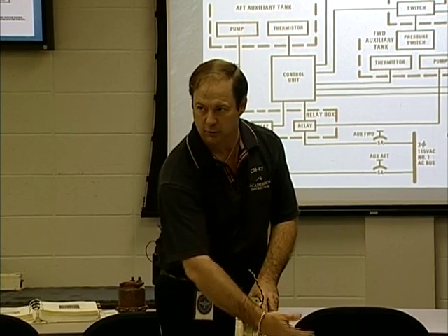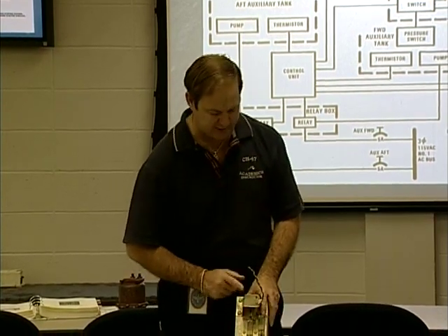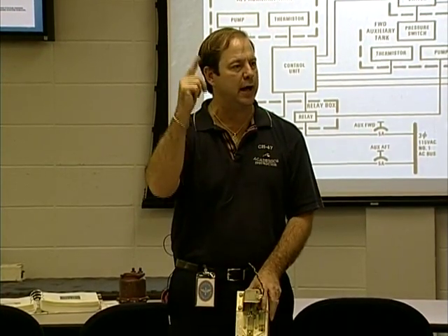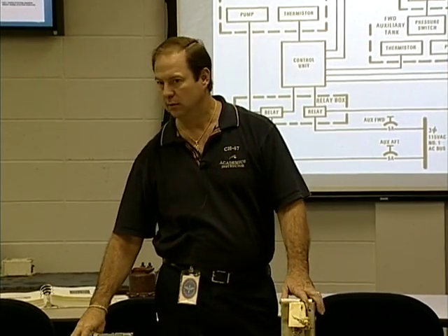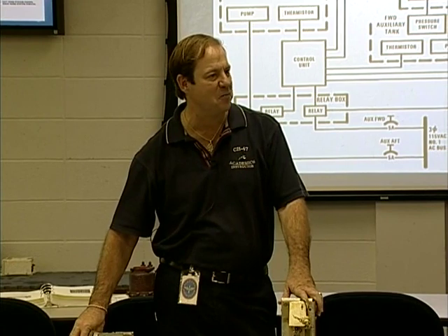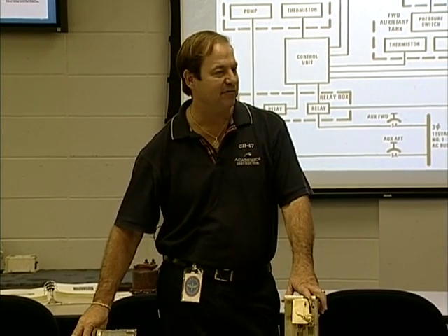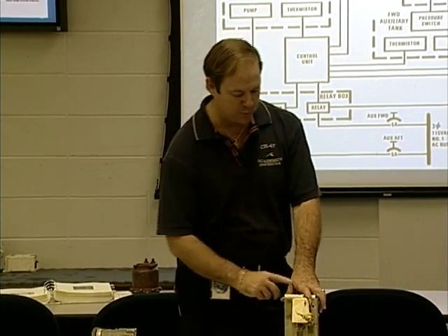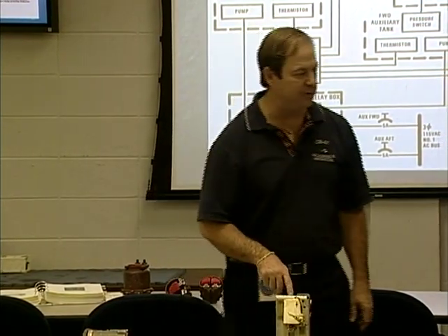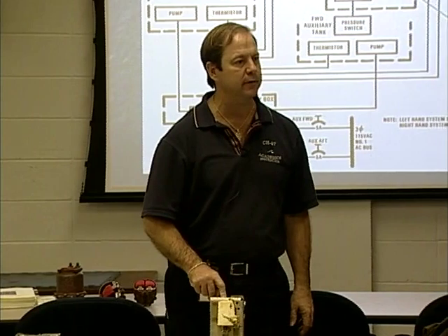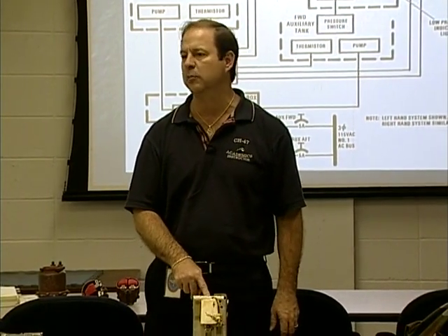It'll slosh, right? And we don't want these pumps cycling on and off. Why? What's left in those tanks? Vapors. What do I know about vapors? They have a very low flash point. If this pump's allowed to cycle on and off, what people don't realize is the fuel that is being moved through this pump is also keeping it cooled and lubricated.